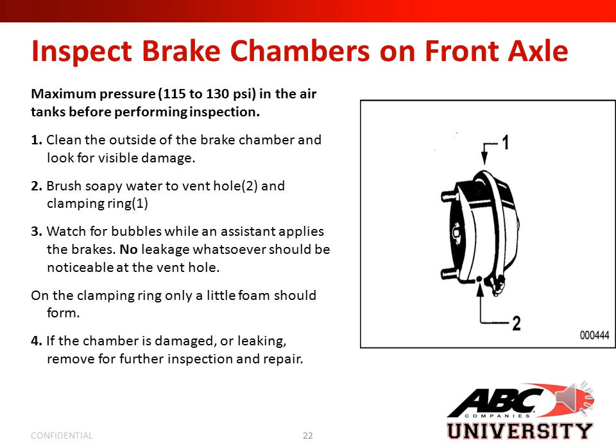Next, we'll talk about inspecting the brake chambers on the front axle. Precondition: maximum pressure 115 to 130 psi in the air tanks before performing this inspection. Step 1. Clean the outside of the brake chamber and look for visible damage. Step 2. Brush soapy water to vent hole number 2 and clamping ring number 1, shown in the picture to the right. Watch for bubbles while an assistant applies the brakes.